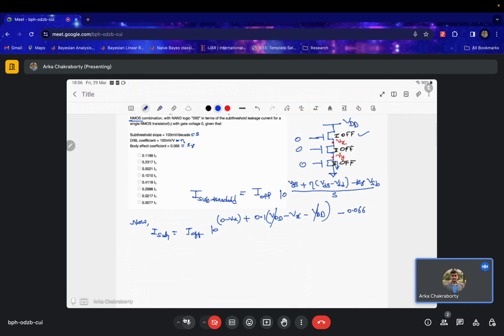Basically these are NMOS transistors, so generally to eliminate the body effect, we connect the body of the NMOS to ground and the body of the PMOS to VDD. Also, if the body-source junction gets positively biased, it becomes forward biased, current increases, and so power dissipation increases.